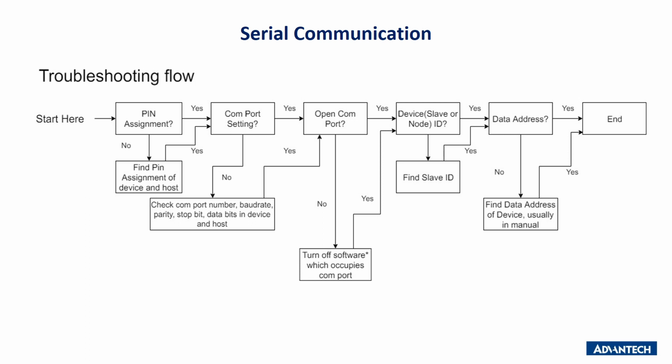Third, please check if there is an error when you open the COM port. A COM port can be opened by only one software. If an error occurs when you open the COM port, there is a high possibility that other software has already opened it. Fourth and fifth, please check if the device ID and data address are correct. They should be in the manual from the device supplier.